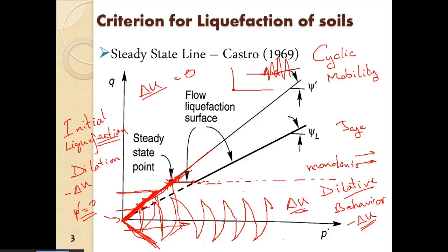So now the soil will actually stabilize, all right, and the shear stress required to cause deformation in the soil will increase with the deformation. So you cannot cause constant deformation in the soil as the shearing continues; as shear strain continues, you have to go on increasing the deviatoric stress or the shear stress.